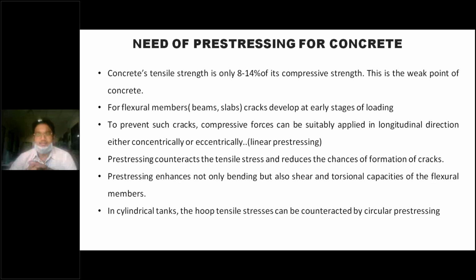Why? Because concrete is very weak in tension. So to prevent these cracks, compression forces can be suitably applied in the longitudinal direction, either concentrically or eccentrically, right? This is exactly what is called linear pre-stressing. Here you are not applying the pre-stressing in the lateral direction. You are going to apply it in the longitudinal direction, in the sense of towards its length, right?